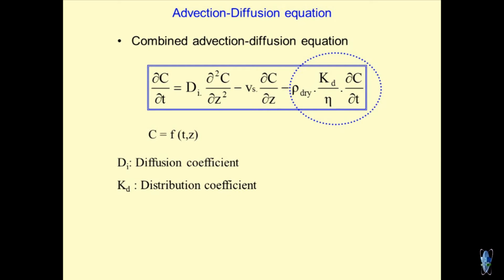So, I can put sensors over there, I can drill the bore logs, I can collect the water sample, I can take out the soil sample and I can establish what is the concentration at this point. In other words, I can know the value of C at a given time and z by doing experiments or by doing field studies, clear, and I can substitute it there. I have to compute Vs, seepage velocity, which is not difficult to do. If I know the discharge velocity, I can divide by the porosity and I can get the seepage velocity.